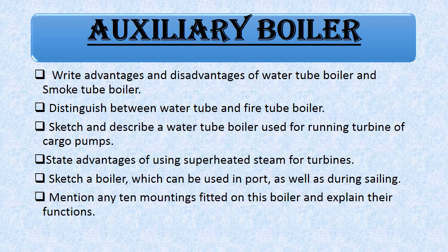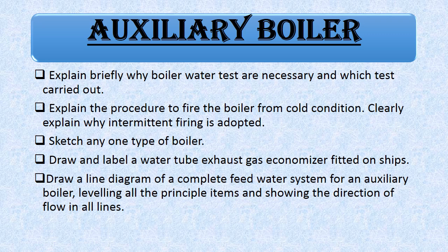State advantages of using superheated steam for turbines. Sketch a boiler which can be used in port as well as during sailing. Mention any 10 mountings fitted on the boiler and explain their functions. Explain briefly why boiler water tests are necessary and which tests are carried out.